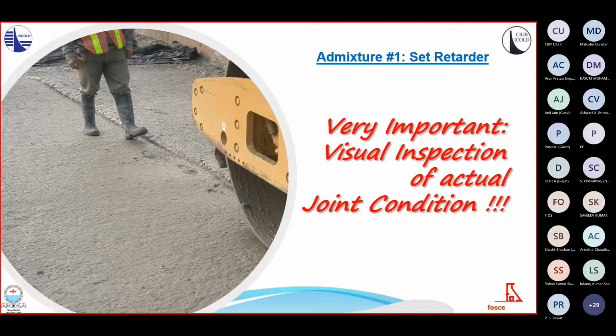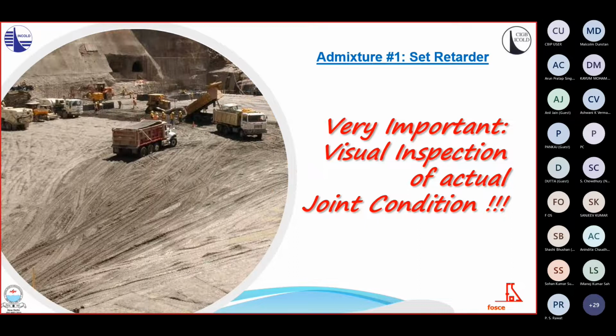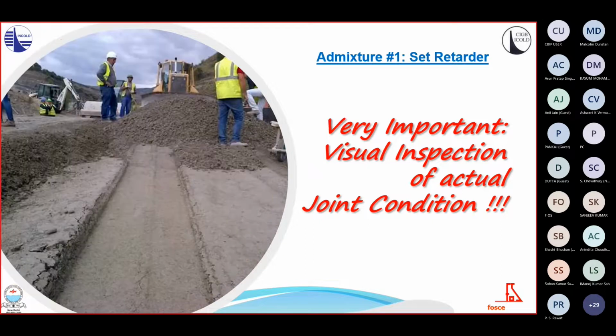These photos show typical good fresh condition of a workable and super retarded RCC. Note the print of the tires of the trucks used for the transportation of the RCC for the next layer. This is a good sign of the desired hot condition and the monolithic bonding between layers.